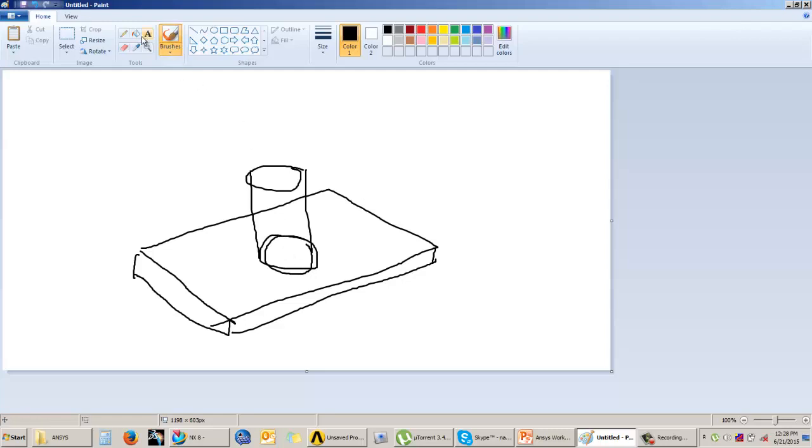Now this is one single geometry that we will be having. Let me erase this over here. Now let us say this is the geometry that you have. Now again, in this case, if you try to mesh this geometry, which is a whole geometry, you will not achieve hexahedral elements because it is not a sweepable geometry and it is not a uniform structure. So on this geometry, if I want to achieve the hexahedral elements, what should we do? We need to convert this geometry into a sweepable geometry or a uniform geometry.